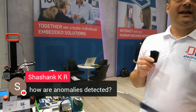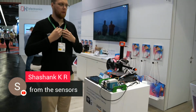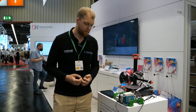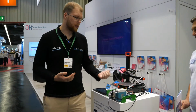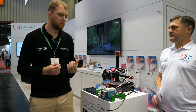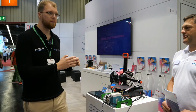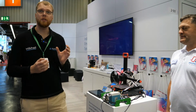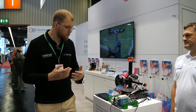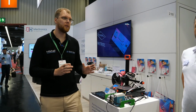How are anomalies detected from the sensors? So for anomaly detection, we are using machine learning, and one of the techniques. In fact, on the controllers, we have a three-head machine learning model. One head is trained using supervised learning for the classification. It's needed in order to understand the normal operation state of the industrial equipment. The other two heads are trained using unsupervised learning, and basically we feed them data, and they make the decision and we provide the anomaly score. We have here two conceptually different types of machine learning model.